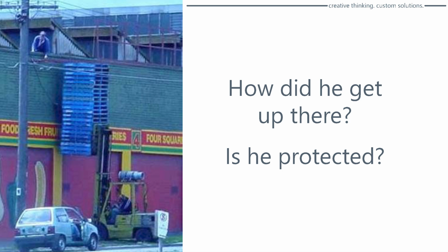Okay. So if you lift people with a forklift, now does it become a personnel lifting device? If so, what's acceptable? Got to go look at some other rules. Can you buy baskets that fit on the forklift? Yes, you can. But look and see if the manufacturer allows you to do that. I know we're a little bit off topic right there, but it still comes back into fall protection and fall prevention. Okay?